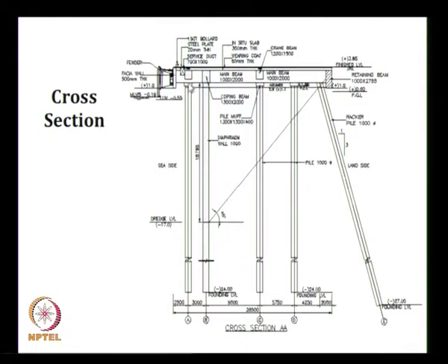This shear will be transferred to the vertical piles and raker piles. But if you have a retaining beam in which you have the lateral force, this will be distributed to all these piles and the diaphragm wall. The diaphragm wall per se will not be subjected to additional bending moment, only whatever shear comes it will take.